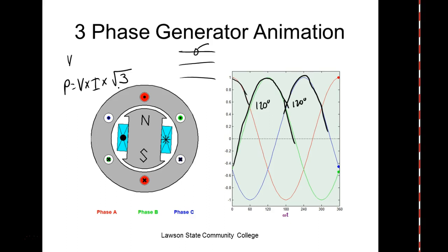Now, 3 wires are very expensive, but if I'm transmitting it, it's easier to run 3-phase than single-phase. But when I get down to low-powered applications where I'm not trying to do a lot of power, then we drop down to single-phase. So your house runs single-phase. But if you go to some big commercial place, it's going to use what? 3-phase, because they use more power, and it's more efficient for Alabama Power to deliver that. So the power savings would offset the cost of the extra conductor.